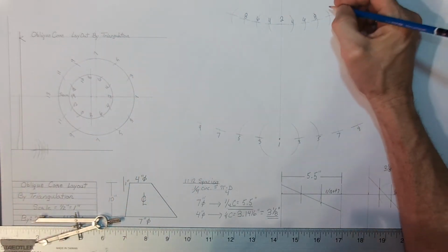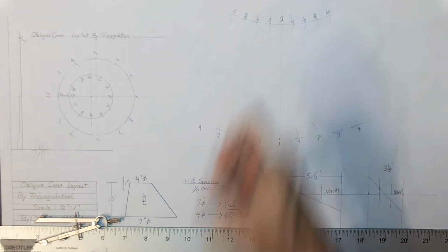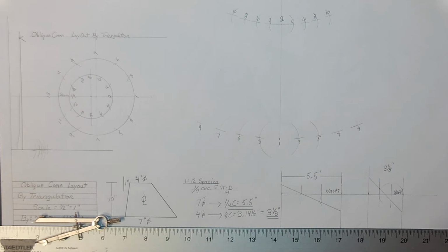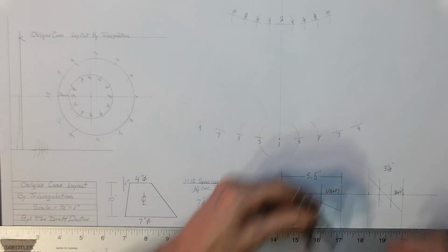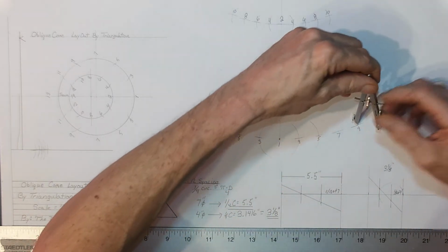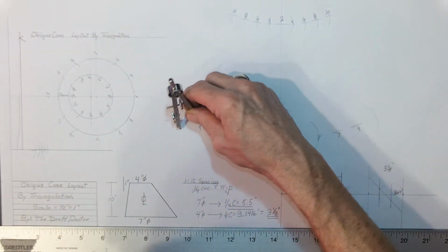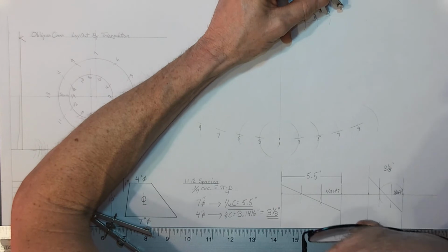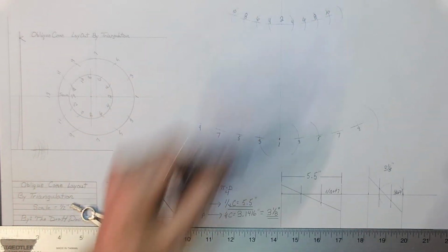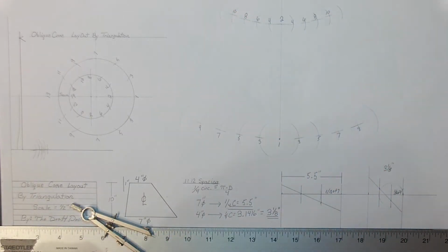Once you get into doing layout on things like Y branches and whatnot, and if they have mitered collars or a sharp miter, you will find quite often that the layout kind of goes all over the place. It makes a nice little wave starting at the center, going down and then coming back up on the wings. And when that happens, a lot of times we think, oh my gosh, I'm doing something wrong here. In reality, there comes a time where we just have to start trusting what we do and believing in ourselves, and the end result is the pattern. A lot of times we don't know whether we're right or wrong until we actually lay that pattern out.